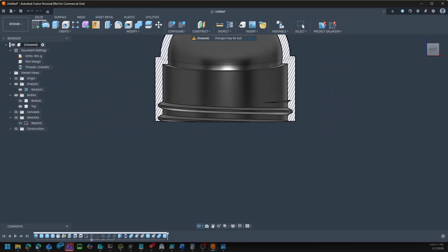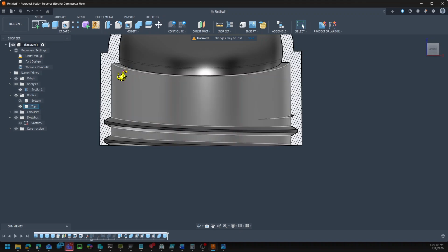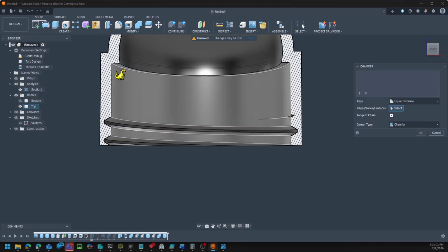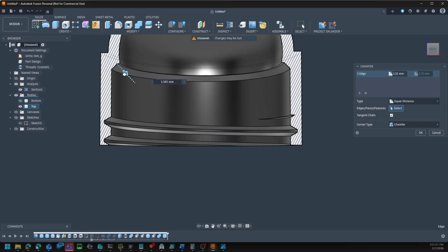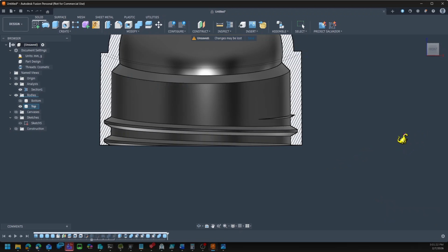Okay. Another problem is this overhang right here. This overhang is not going to want to print because it's at 90 degrees, and most 3D printers can only reliably print overhangs up to about 60 degrees. So I can chamfer this face by some value here. And it looks like if I do 2.1, fine, 2.2, 2.3. Oh, 2.3 gives me an error, so we'll go back to 2.2. There. Okay, so now that is 3D printable.